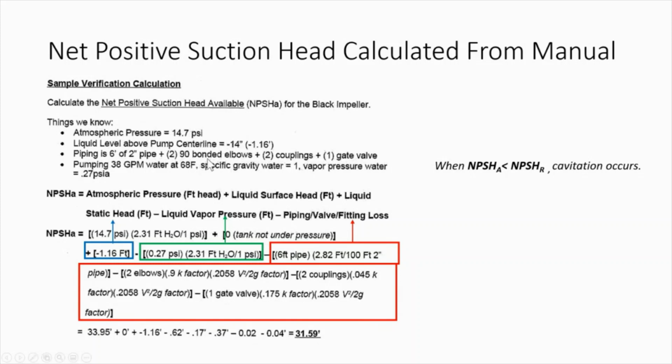Then for each elbow or for each coupling, you will have a pressure coefficient. So if you have 2 elbows, you just multiply that coefficient with this equation in here with the velocity of it, and then you get the minor pressure drop or minor losses. So pretty much that's it. That's everything that you need to calculate it. You just plug them in and you'll get a value.